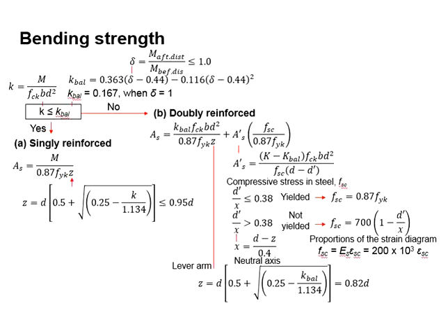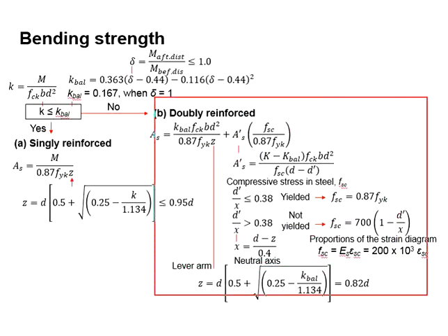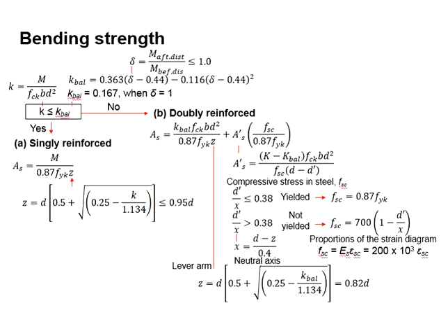When the compressive stress exceeds the capacity of the concrete, you require compression steel bar to strengthen the concrete in resisting the compressive stress, so that the member does not fail in compression. In other words, theoretically the doubly reinforced member is stronger than the singly reinforced member, although the cross-sectional area of the member is the same. You can interpret it in this way.